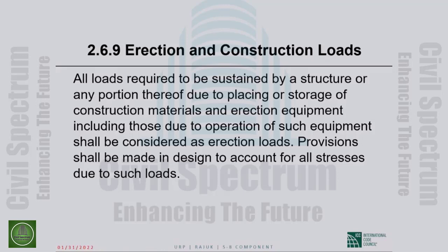There is no formwork in the picture. And those reshores should be kept in place for quite some time in order for the slabs not to deflect too much under these construction loads, the stored material with people walking around, etc. So that's how construction loads are. Bulk of it is treated.